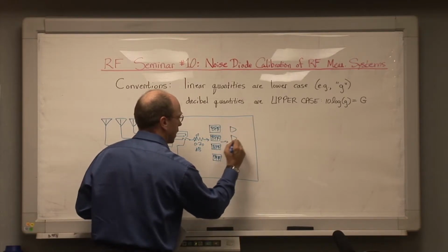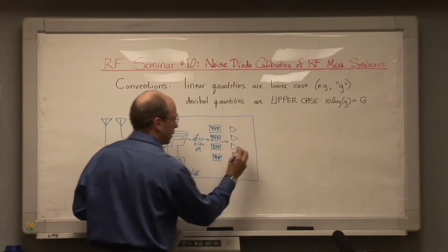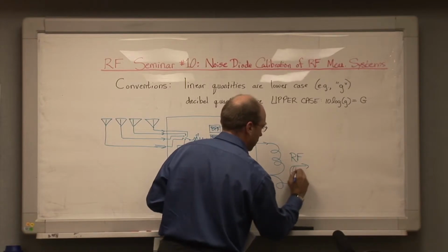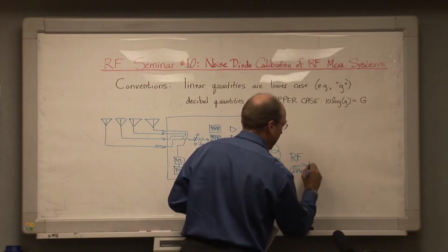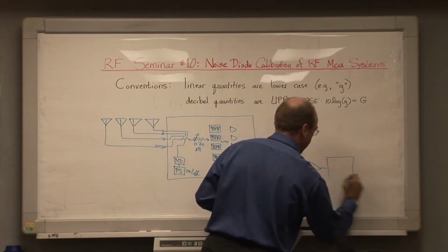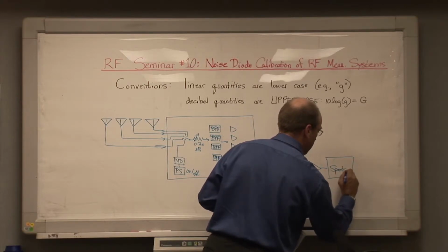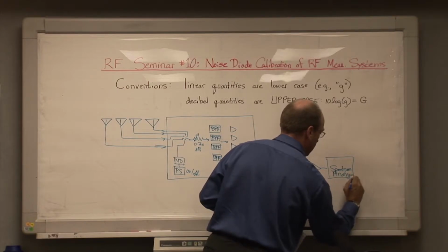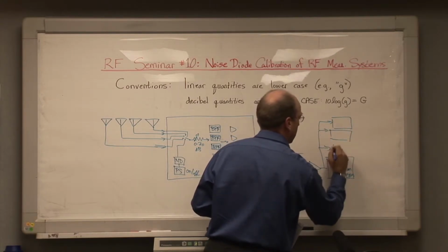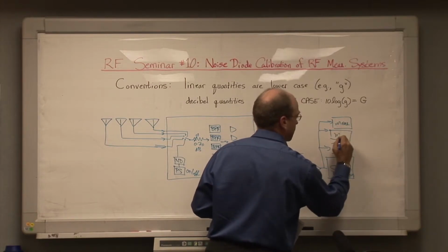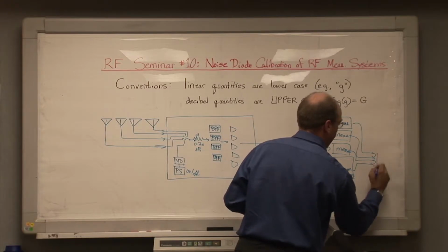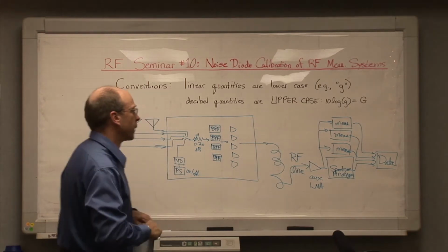We then go into any one of a group of low noise amplifiers in the box, and then coming out of the low noise amplifiers, we then pass down through some kind of RF measurement line, hopefully a little straighter run than I just drew, and then possibly into an auxiliary low noise amplifier and any other components that we might need. And then typically at this point we'll run into a spectrum analyzer, or any one of a set of ancillary measurement boxes, for example, oscilloscopes, etc. And then finally we wind up with our final data output at the end of the system.